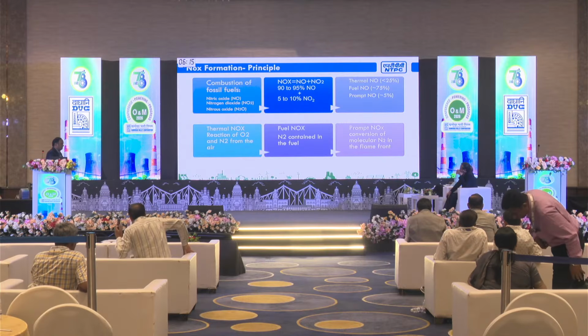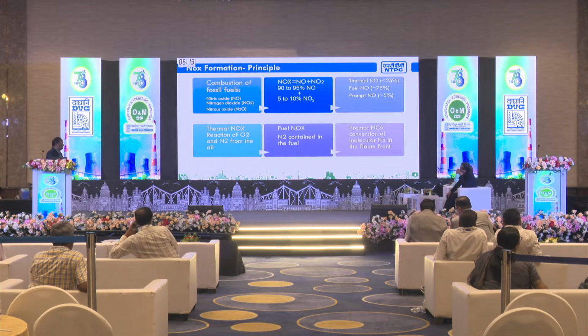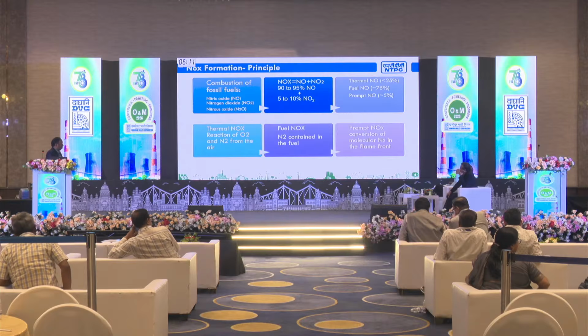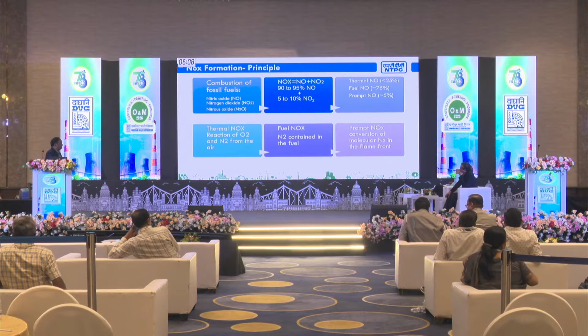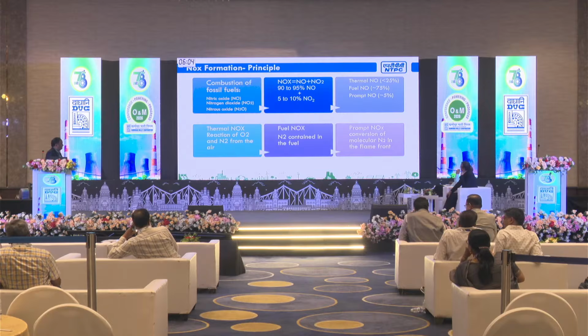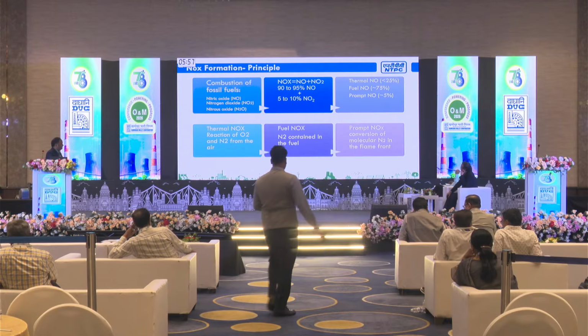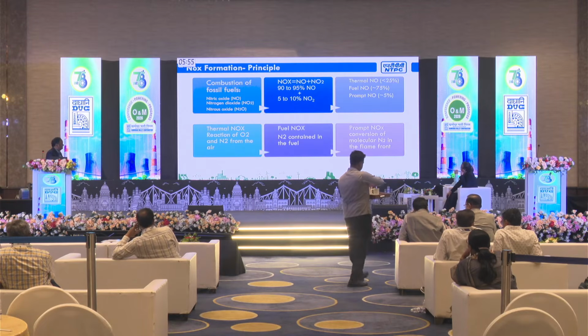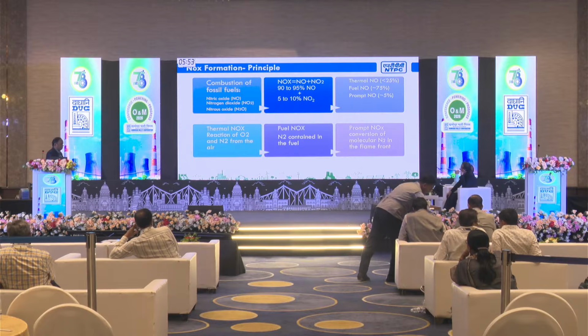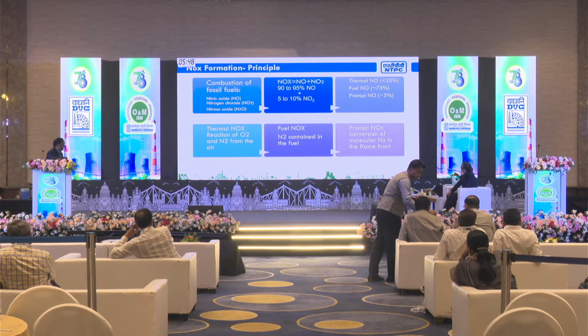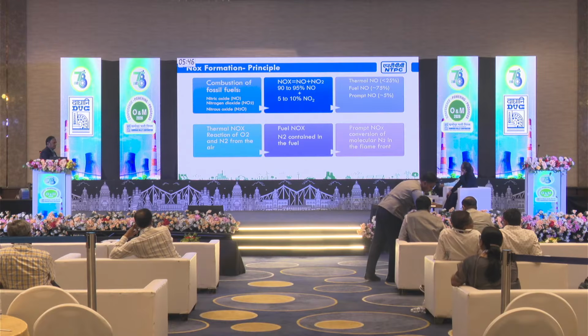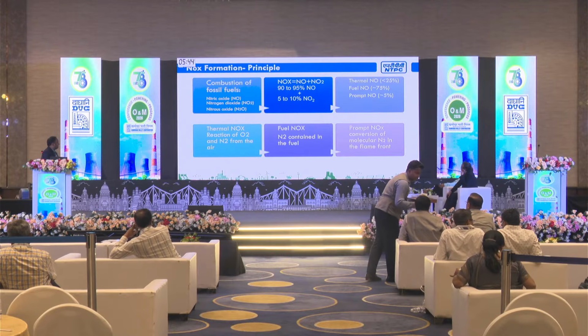And further, NOx can be divided into three parts: thermal NOx, fuel NOx and prompt NOx. Fuel NOx comes from the combustion of fuel, by the reaction of nitrogen which is present in the fuel, whereas thermal NOx is the reaction of nitrogen which is present in the air in an oxygen-rich environment.